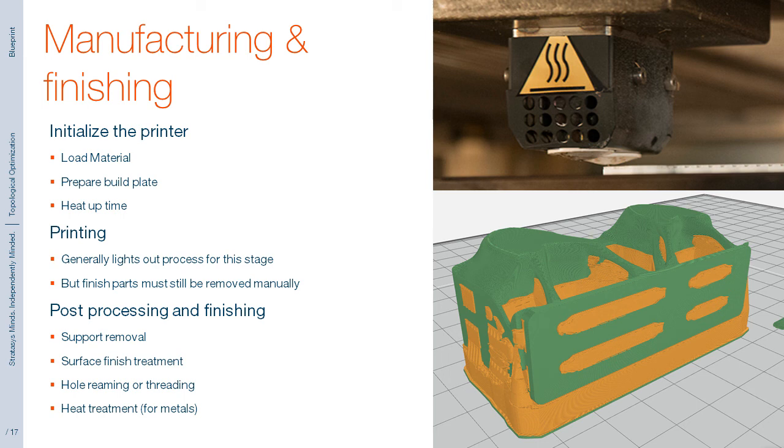For example, any support material must be removed. Generally, the high-performance polymers only have breakaway support material, not soluble, because of the high temperatures involved in printing them. Additively manufactured parts generally have rougher surface finishes than traditional methods, so if surface finish is important, manual sanding or automated vibratory polishing might be required, especially on mating or sliding surfaces.